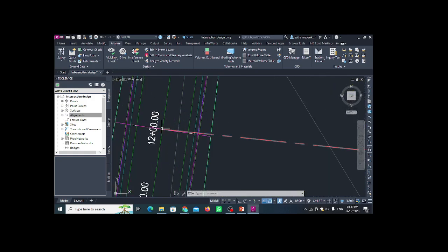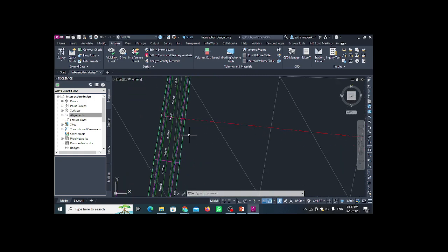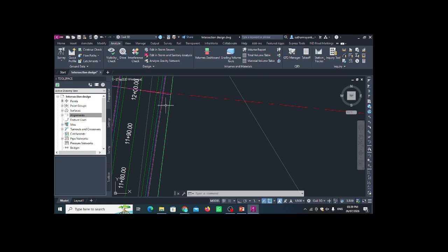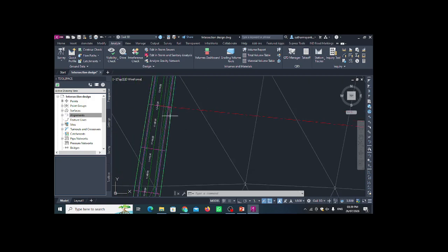As we have the zero, but zero chainage is here. So this one is our right part. Inside we have the roads at this side, and this side we have the side assemblies and daylights and curb and gutter and that type of things. So if our road chainage zero is from here, then this one is our right side and this one is our left side. So on the right side we have to provide this part. Even if you make a mistake, it is very easy to change. It is not a very big issue, but you have to create the assembly properly.